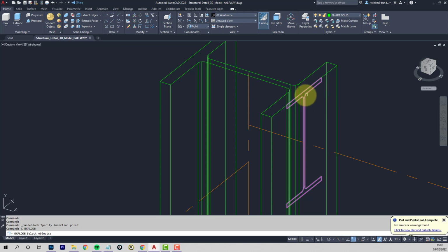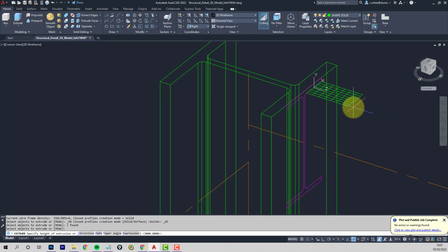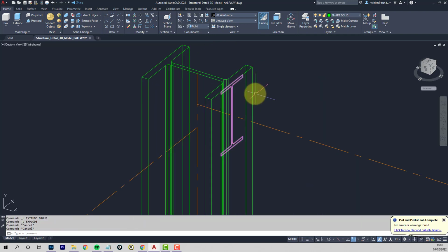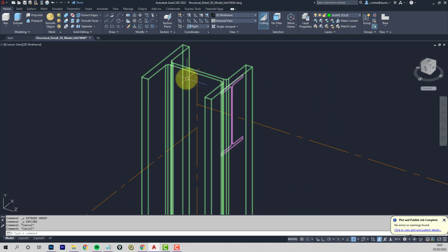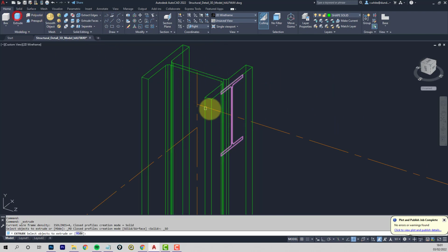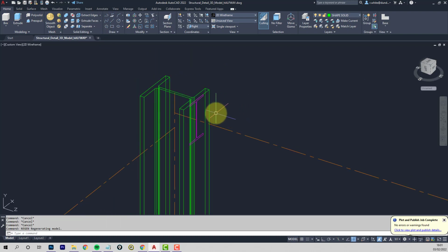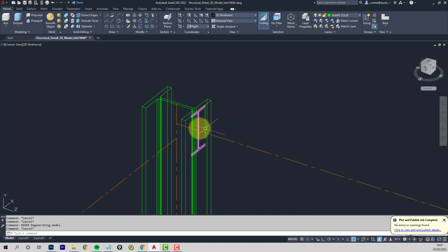Okay, because it's been pasted in as it is a block, we need to explode it first. X, enter, click, enter. Don't explode it again or you'll stop it from being a polyline, and if you do that and try to extrude, you get this appearance. Okay, that kind of indicates that it's not a polyline anymore. When it's a clean closed polyline you don't see any of that gridding. So extrude. Let's start that again. Seems to be kind of highlighting automatically.